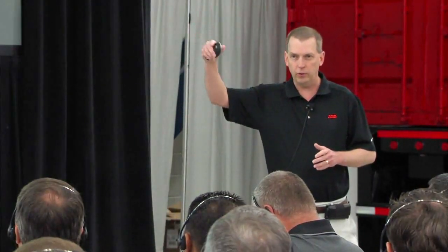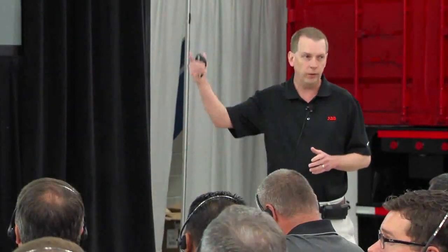You tell the drive, I want you to go learn everything it can about that motor. And it runs through a tuning algorithm. It'll lock the rotor for a while, then it'll run it up to full speed, and it'll decelerate it down, and it might do it again. It tries to measure the characteristics of that motor and log those parameters into its memory. Now it knows about the motor, and it can estimate the speed more accurately.